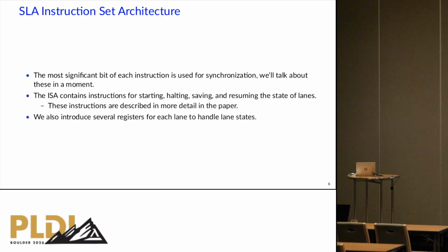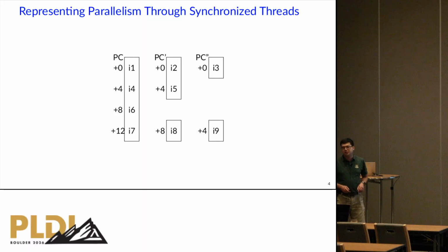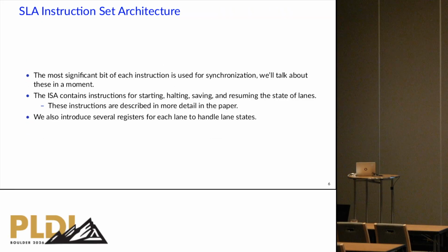And it has a bunch of instructions all dedicated to spinning up instruction streams, as well as halting instruction streams as we go, entering functions, and so on and so forth, because a couple things are going to change. We won't be able to get into that, but if you're curious, you can read about it in the paper. We have several registers as well that are really there to administratively say, are you running or are you not running, for states, as well as if we enter a function, normally we have to keep track of one PC. Now we have to keep track of a handful of PCs. So we have extra registers for that.